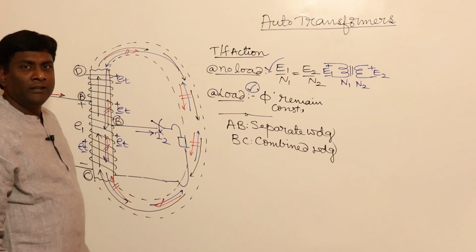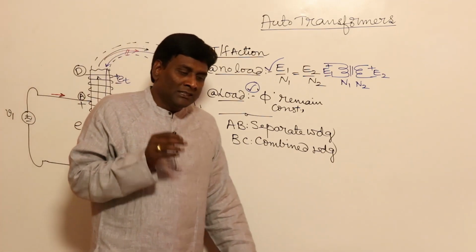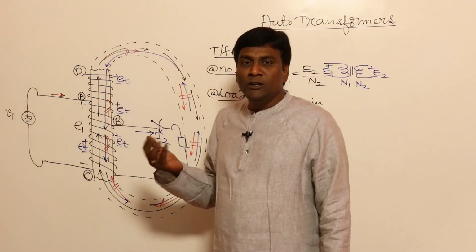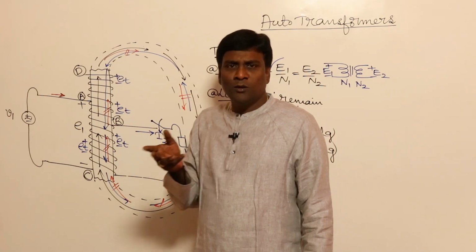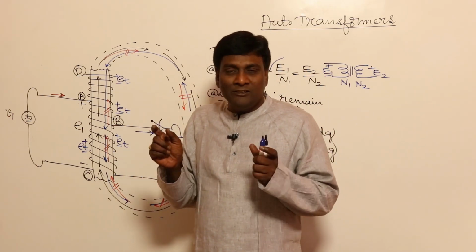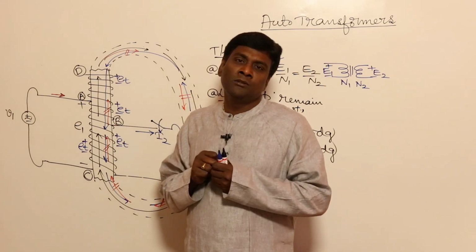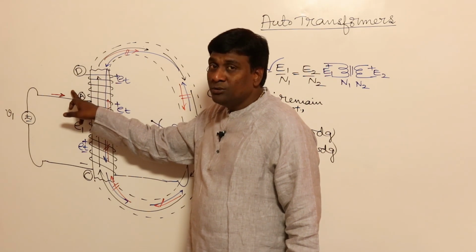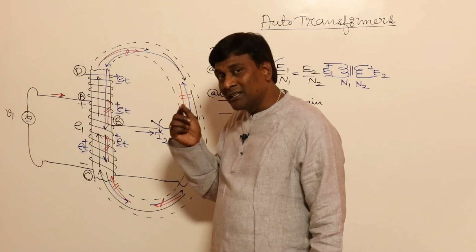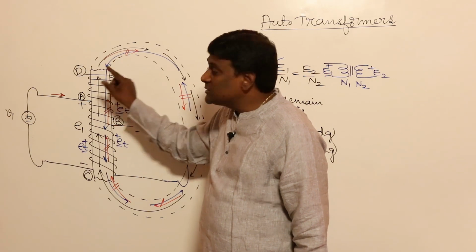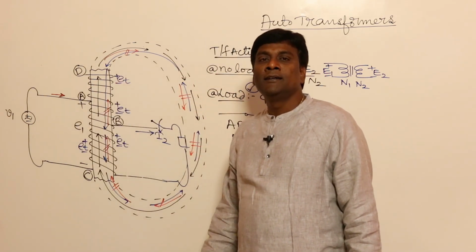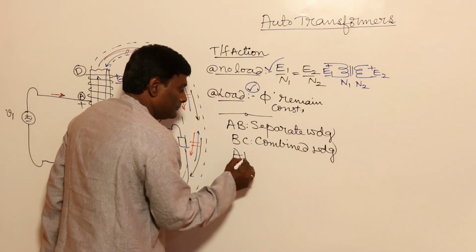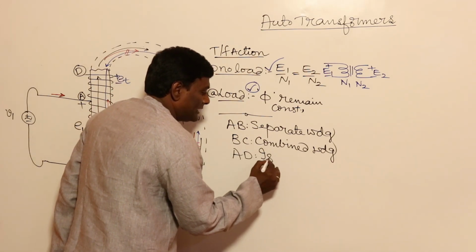Yes. Basically, let me tell you the difference between Ohm's law and electromagnetic induction. In Ohm's law, V equals IR. If you have current, voltage will be there. If you have current of 0, voltage will be 0. But in electromagnetic induction, how much current is flowing in AD? 0. There is no current flowing in AD, but still voltage is induced, because that particular turn is influenced by change of magnetic field. So this AD, let me write it as an isolated winding.